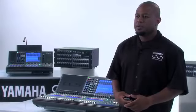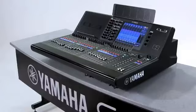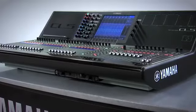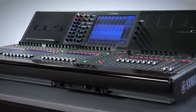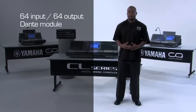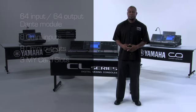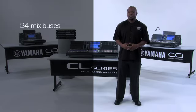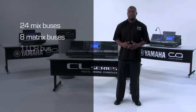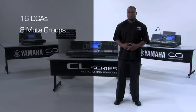There are three consoles within the CL Series digital mixer lineup: the CL1, the CL3, and the CL5. Each one of these consoles has some common features, including a 64 input, 64 output Dante module, 8 Omni input ports, 8 Omni output ports, and 3 MY card slots. There are 24 mix buses, 8 matrix buses, and an LCR bus, 16 DCA faders, and 8 mute groups.